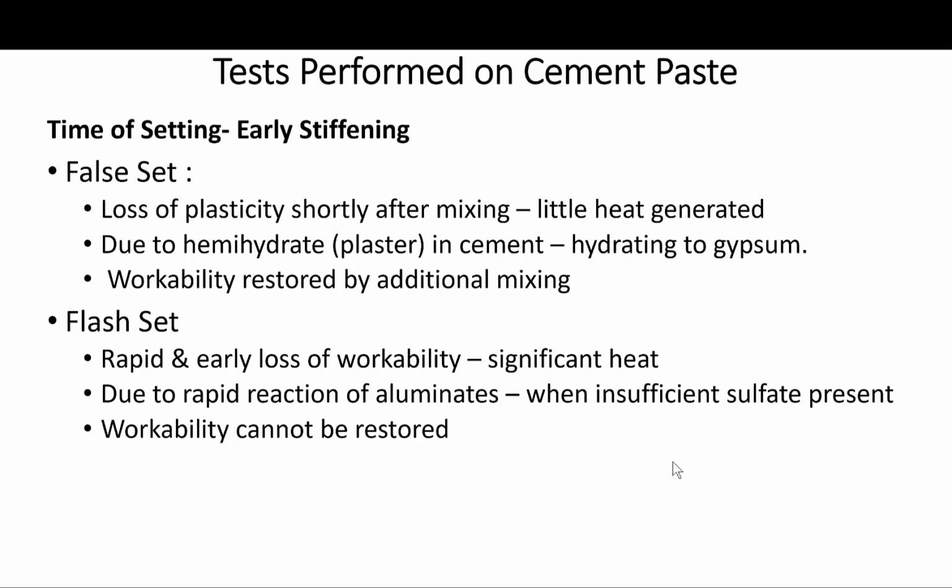So again, this flash set will be an indication of undersulfated cement or other issues of solubility of the sulfate, the form of the sulfate present in the cement. So this test I consider important, and I will look for that test just to make sure this is not an issue.